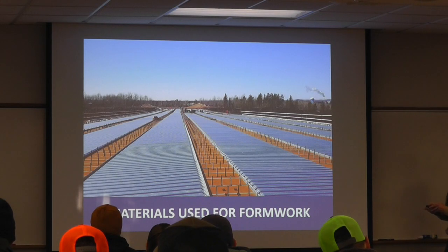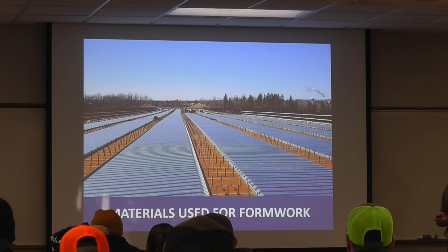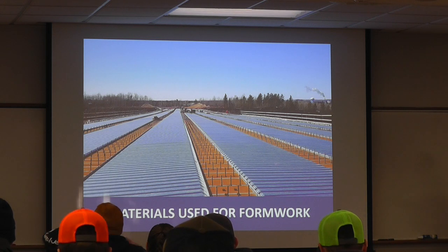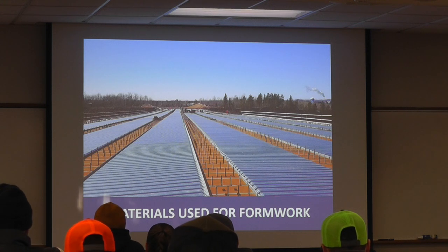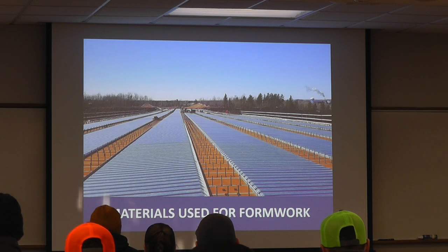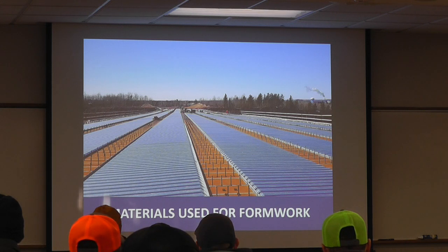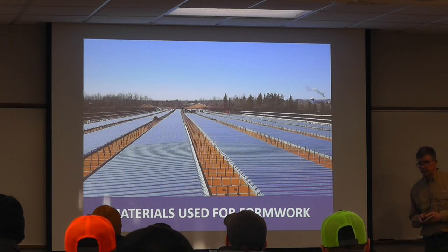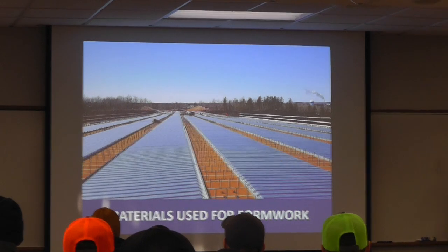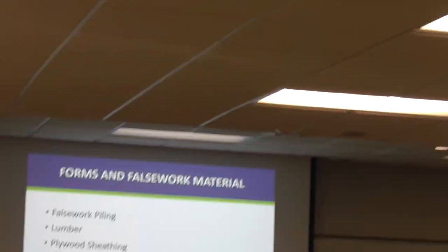Okay, so let's take a look at some real-world examples. This is something we don't use in Minnesota. It's stay-in-place forms at the bottom of a deck. The reason we don't is it's been so difficult to be able to inspect what the concrete is doing. I don't know, maybe someday we'll see more of that. Right now, they're not allowed. But it's a lot of labor for the contractor to remove the underdeck forms. And so if there was a way that they could just keep something in place, it would save a fair amount